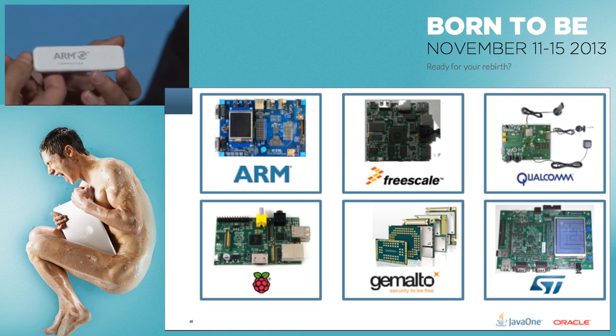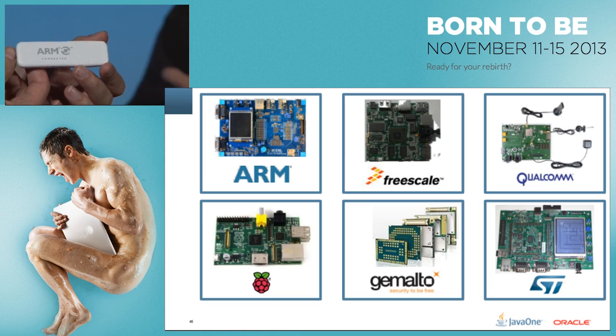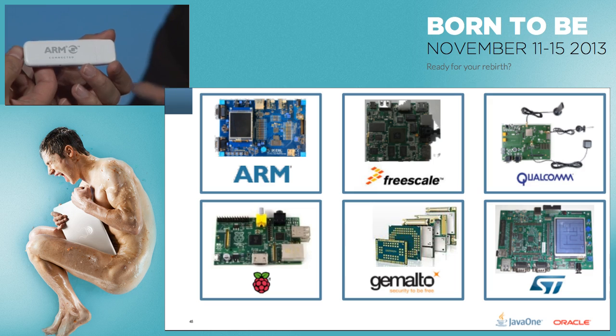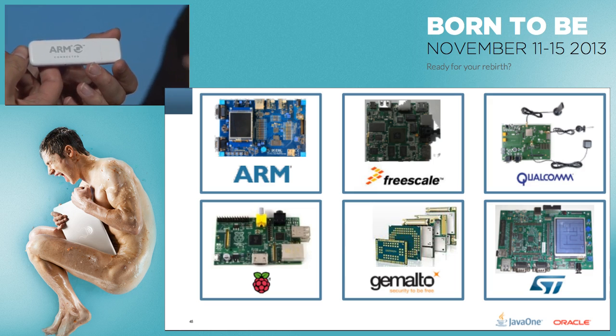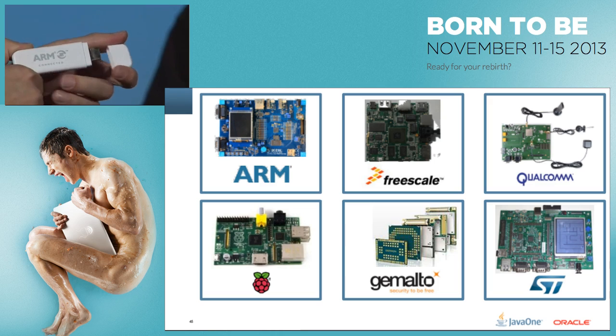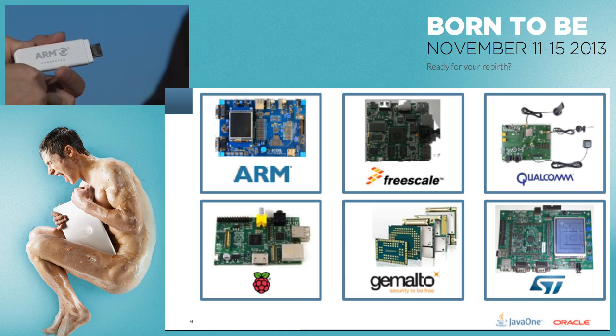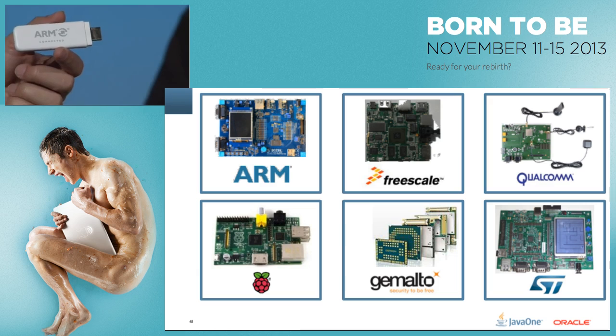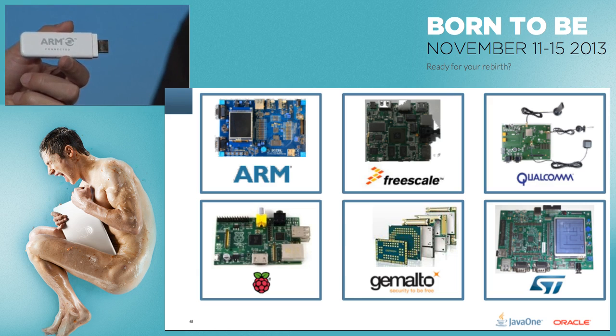So that system there has a dual GPU for graphics, Mali 400. It has a dual Cortex A9 CPU inside it. So it's 1.2, I think, gigahertz. It's got, I think, 1 or 2 gigs, 2 gigs, I think, of memory, and an eMMC of either 8 or 16 gigabytes of memory.